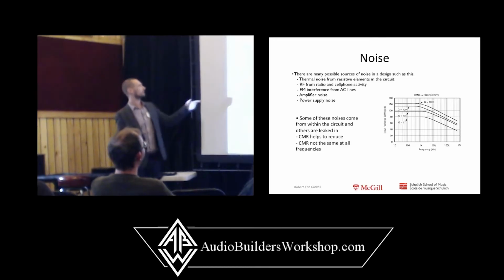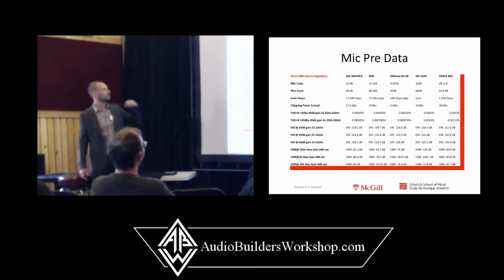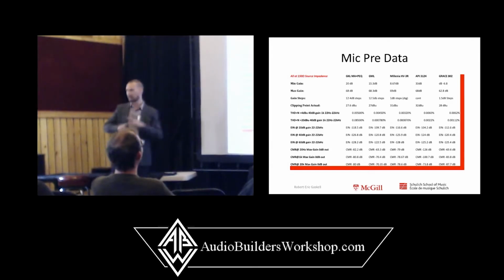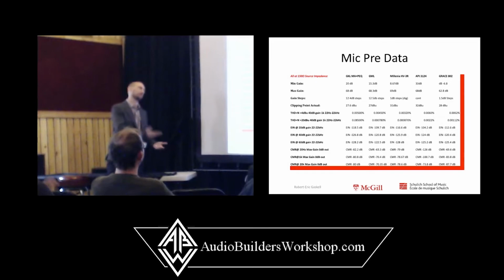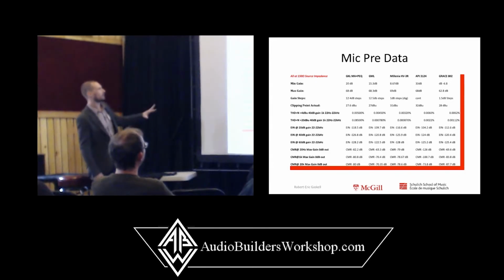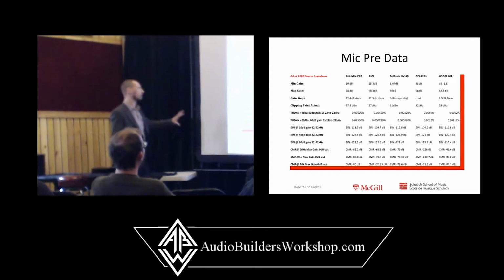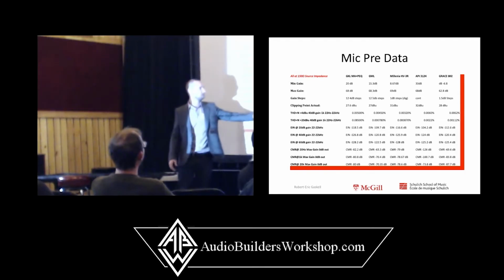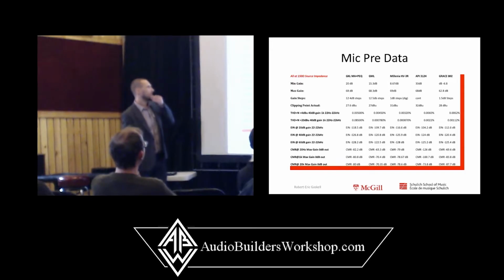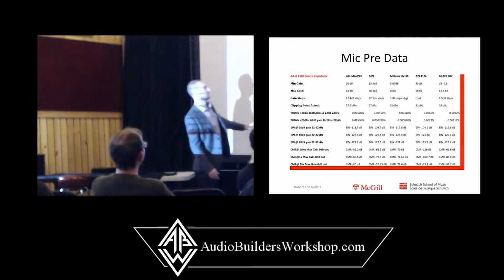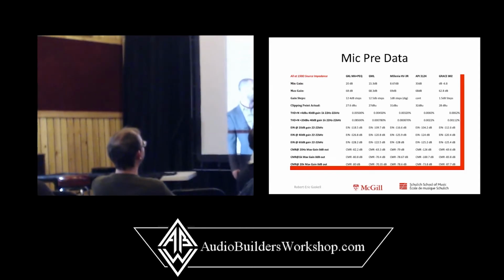Yeah, so I guess the big point I wanted to make here is that not all common mode rejection is created equal, and common mode rejection can be frequency dependent. Let's go to the next one here. This is some data. I keep a running log of data of any microphone preamplifier I ever get my hands on. I do the same set of measurements on each. And I'll call your attention just for the moment to the common mode rejection of a few different mic pres here.